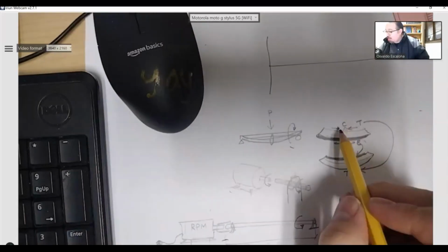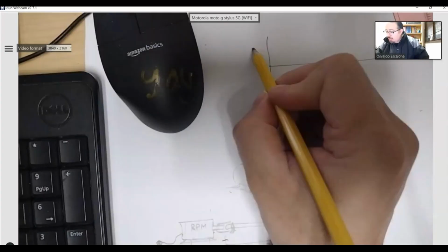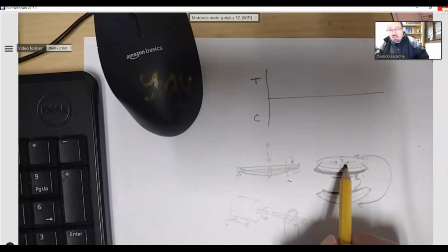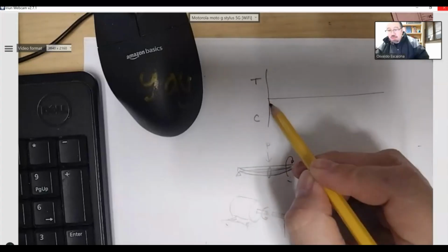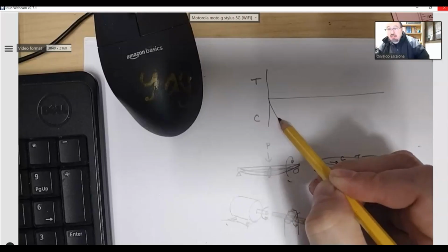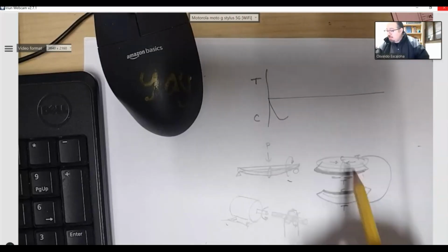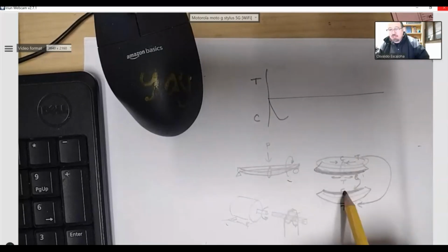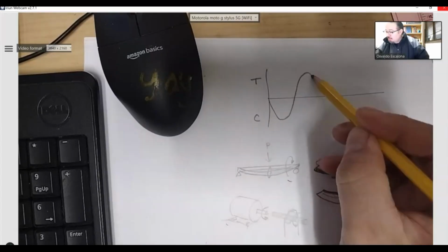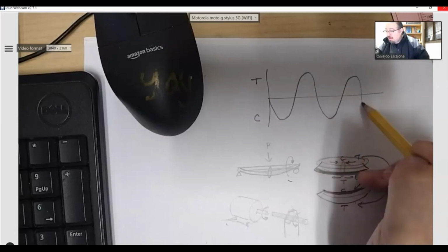If I were to look at one of these fibers, and call this one tension and this one compression, the top fiber started with compression, and the compression increased as my shaft rotated, eventually switching from compression towards tension. But remember, it flips sides, and it's doing this back and forth, back and forth.